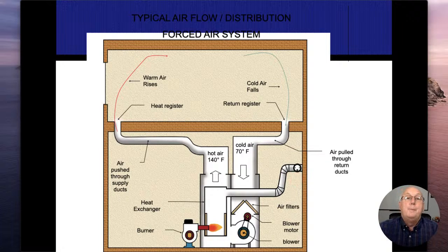All right. Now, airflow into forced air furnaces is important. And it should always be the same way. Now, they're showing this where it almost looks like the vent or the vent connector is going through the return air. Yeah, there was a very short time frame where that happened, but we don't do that anymore. Pressure differentials are very important in the safety of how these heating units work. All right. So first thing we want to do is talk about the airflow.